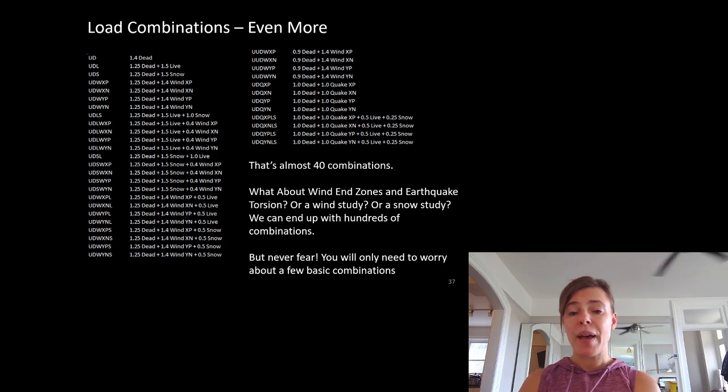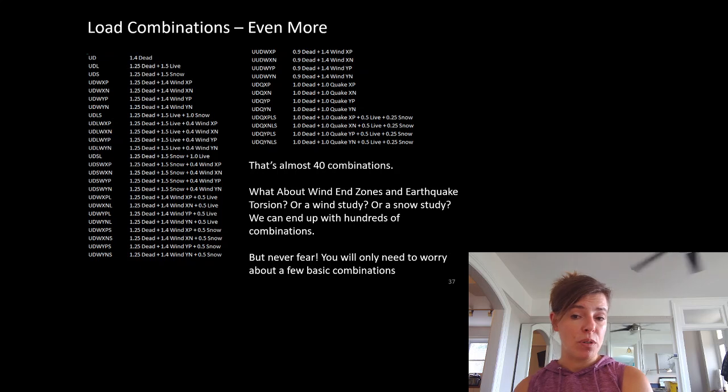I've done projects where, on top of that, we might have a wind analysis done of our building or a snow analysis done of our building. That Canadian Peace Bridge Plaza that I showed you at the border crossing, we had snow and wind analysis done of those. I ended up with over 1,200 load combinations that needed to be considered. And every time we made a change in the design, strength and stiffness needed to be recalculated for every element, every connection, and every system on the building. So that starts to be a really kind of rigorous process as we go through the design.